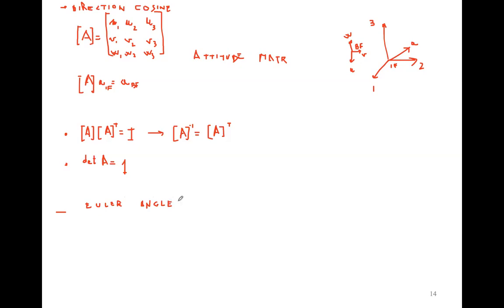If you want to represent a specific orientation of the spacecraft using 3 separate rotations, for example 1, 2, 3 or 3, 2, 1, you have possible singularities that affect your attitude determination, because for that representation you're not able to have a solution. So we are not going to look at that in particular. There are ways to avoid singularities with Euler angles.